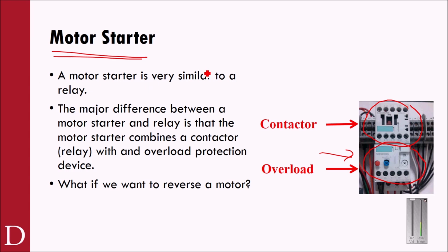The trick with a motor starter, though, is what if we want to reverse a motor? Well, the only way to reverse a motor is really to have two motor starters then. I would have motor starter 1, and I'd have L1, L2, and L3 that would get sent down to the motor.